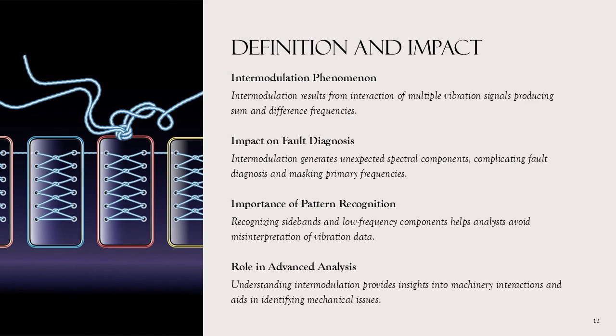Analysts must recognize intermodulation patterns, which often include sidebands or low-frequency components, to avoid misinterpretation of data. Understanding intermodulation is essential for advanced vibration analysis, as it provides insights into complex interactions within machinery and helps identify underlying mechanical or structural issues.